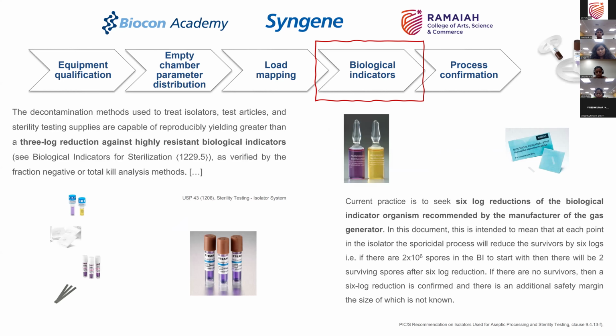You will use biological indicators, of course, for VHP, heat sterilization, etc. Only in case of gamma irradiation, you can't do that. So you will do a bioburden pre and post. And then, based on the biological indicator load mapping, you will place the biological indicators in the worst case scenarios and run the process, and you will keep on running the process consistently at the parameters that you set. Very, very important that each and every parameter which affects your process of sterilization is mapped properly.